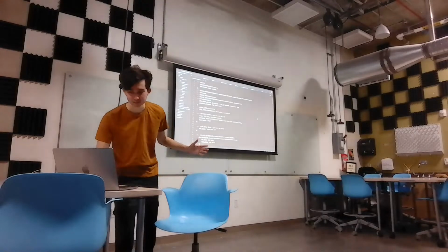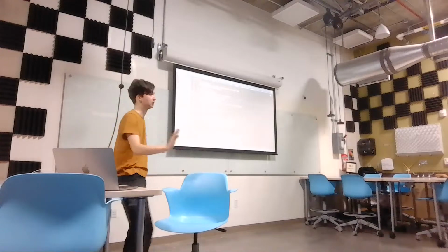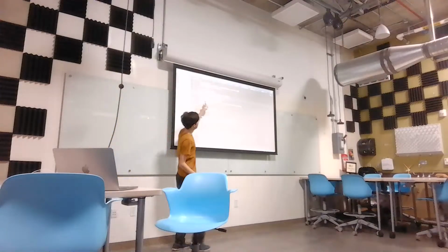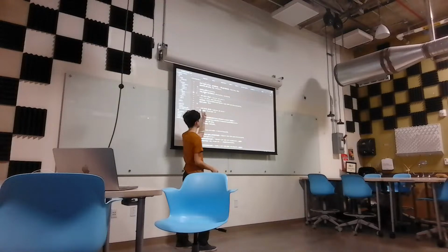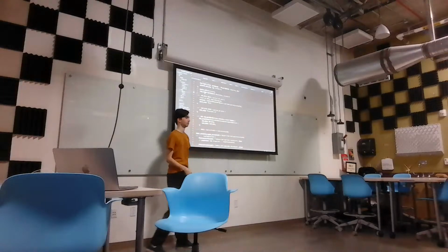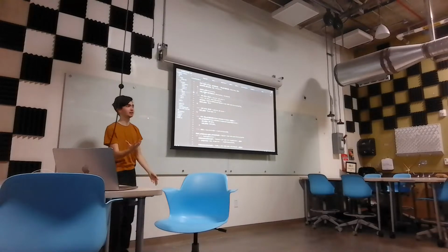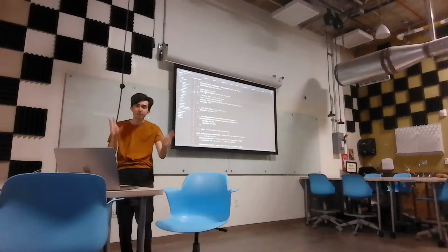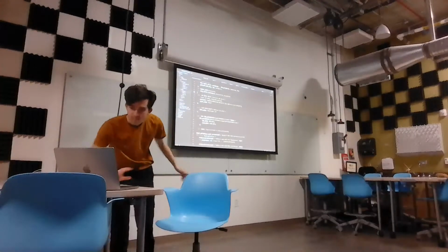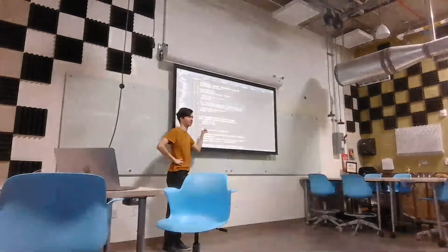But I did it. Look at this. This is our advertisement data. I called it ABV data. Here's the flags, here's the service UUID you're advertising, here's the short name. And then once you're connected, if I scan more information, here's the full name. Wow. That was easy to understand. It just kind of says what it's doing. I don't have to make raw bytes every time. But guess what? If I hover over this, it says it's equal to an array of just bytes. Where did those come from?